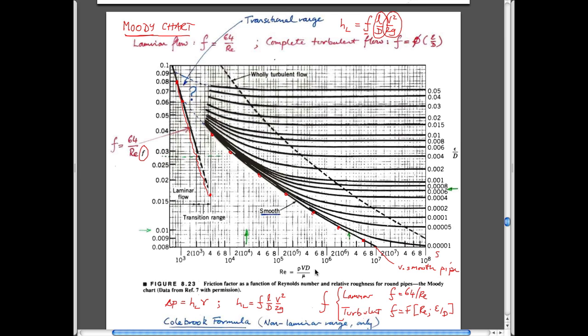You give it a velocity which is equivalent to some Reynolds number. You know how long and how wide your pipe is. You measure what the pressure drop is across the length of the pipe, and the only unknown you have is a friction factor. And so for every experiment you do at every velocity, you measure the pressure drop and you get this friction factor. So you're able to get these points on this graph. And so by using non-dimensional variables, you hope that when you now double the diameter of the pipe, your results should still be true. That's basically the idea of dimensional analysis.